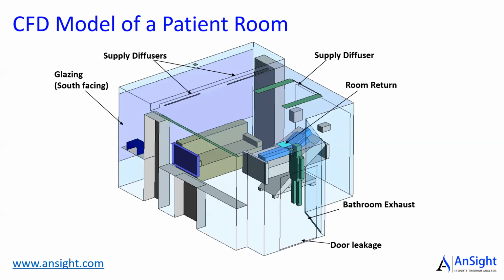So for ventilation, of course, there is a large window here, and the sun may come through that window and can make the room hot. There are two supply diffusers. We call them linear diffusers, like a slot, and they throw the air on the hot window there. And then we have one linear diffuser here, another slot that will supply the air to the room.